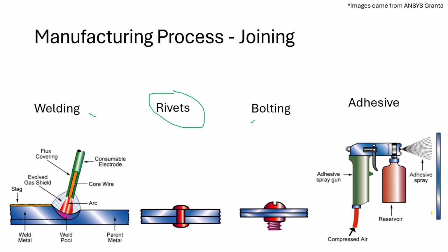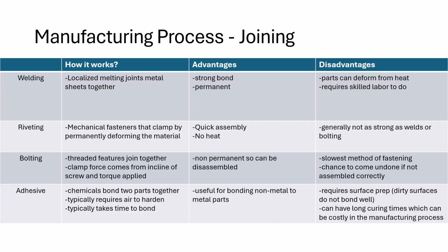And adhesives, I think the big issue with them is that you're either going to have a really long dry time, which means a longer, more complicated manufacturing process, or the dry time might actually be really, really quick, at which point you're not going to have much time to set the two parts together, and unless you have good alignment features, you're going to possibly screw that process up a little bit. So I would say let's avoid adhesives in your design unless you absolutely have to.